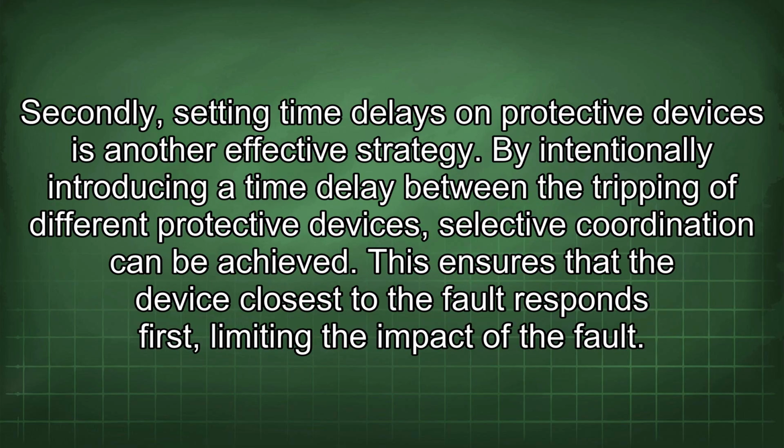Secondly, setting time delays on protective devices is another effective strategy. By intentionally introducing a time delay between the tripping of different protective devices, selective coordination can be achieved. This ensures that the device closest to the fault responds first, limiting the impact of the fault.